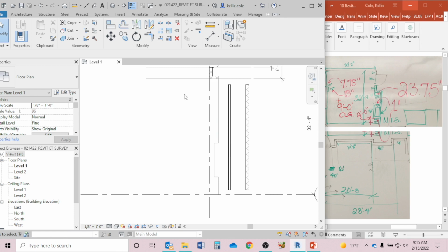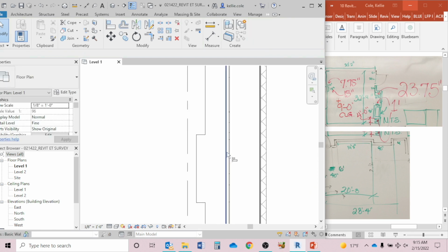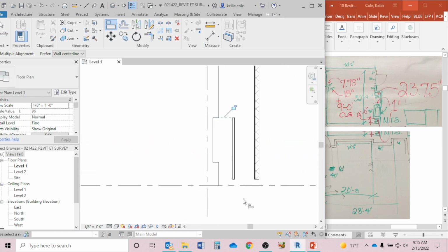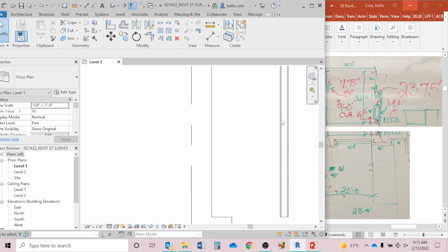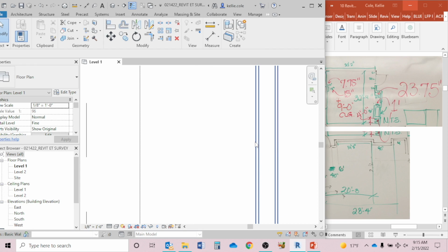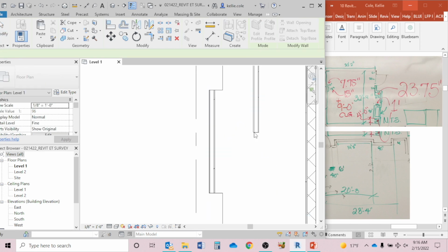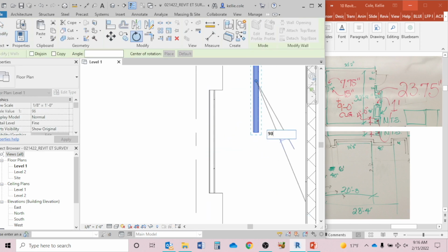But what we really need to understand is that the detail line I just drew represents the inside face of the wall, right? Because I'm just going to align this shaft using AL. Because if we look at the wall and then we think about a plan, it's this inside chipboard face that I'm touching. And it's this inside line that I measured. So every time we align, we're going to align to that face. I know that the top and bottom edges, I'm just rotating, hitting 90, enter.